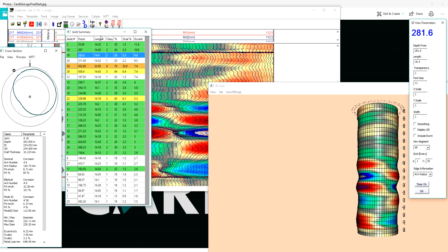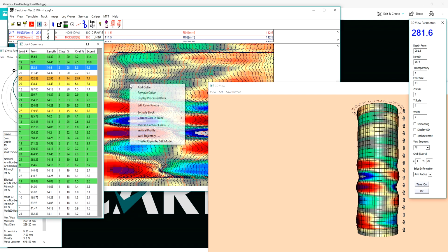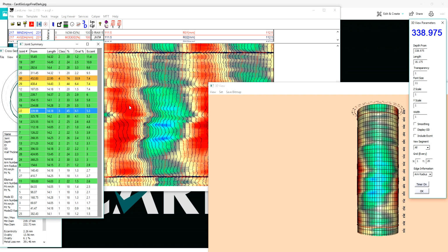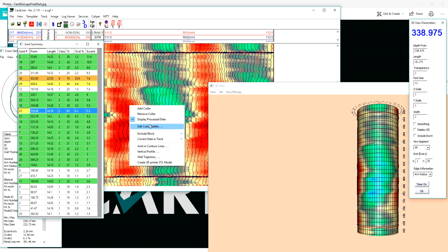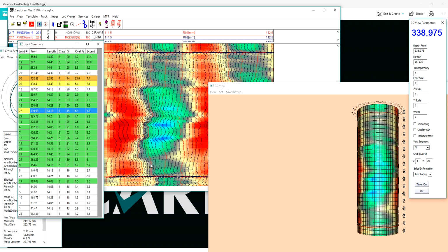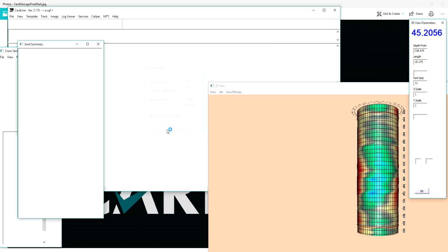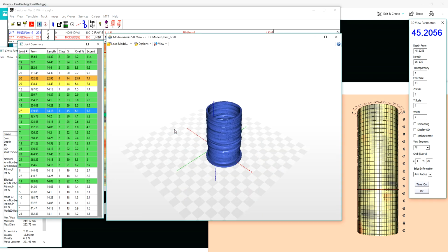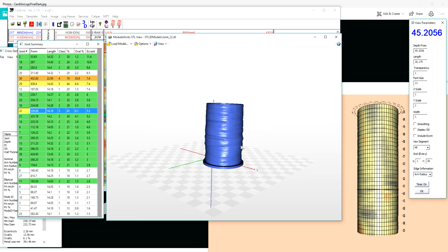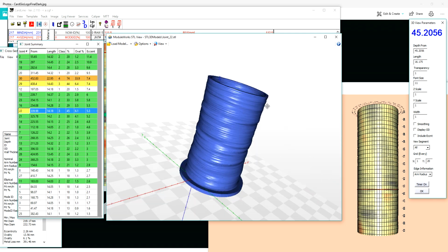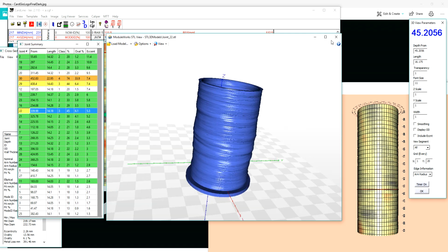You can then create a hard copy of any joint by clicking the right mouse and then selecting the Creating 3D Printer STL model. Here we can assign the exaggeration parameter, for example that of a coefficient of 3. You can now print this model on a 3D printer. The corresponding STL file is saved in the data directory.